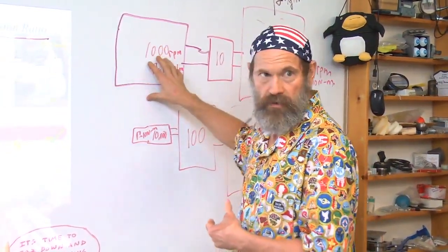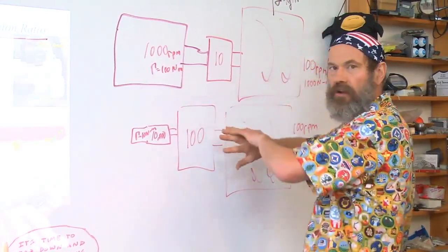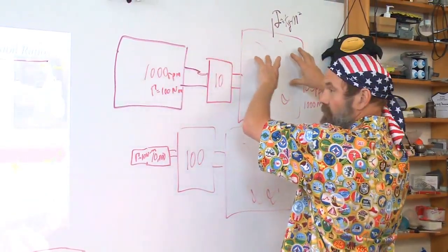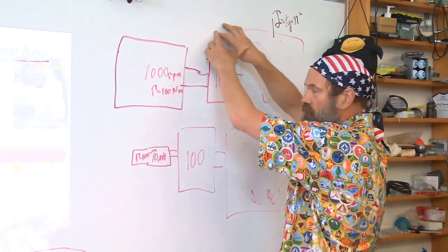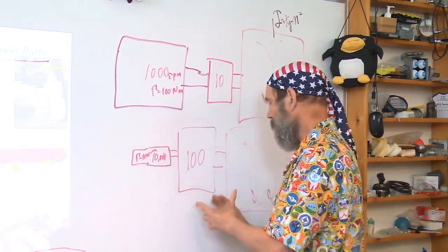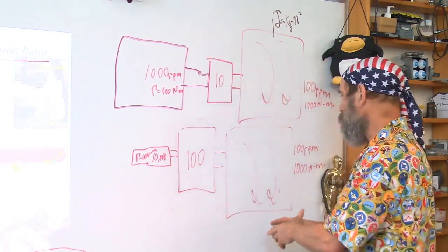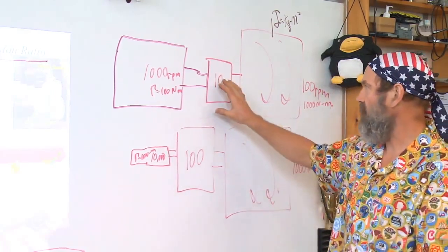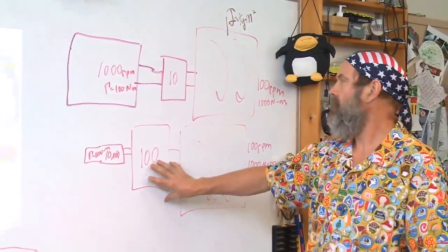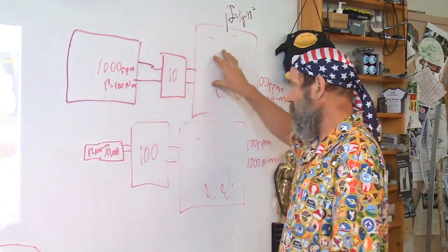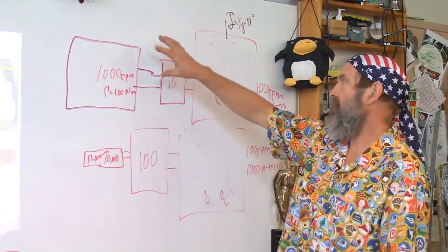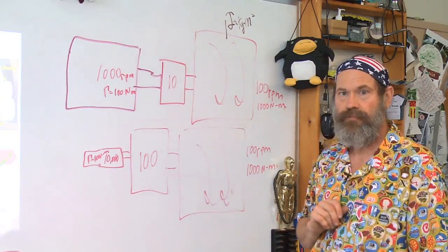So when you go to pick the motor and the load and the gearbox, they all have to work in harmony. You can start by picking a motor. Well, you have your load and see what transmission ratio that gives you. And then you can go to the other extreme, the higher speed, lower torque motor. What kind of transmission ratio is required then to drive your load? And what you'll find is that sometimes you'll get very unreasonable transmission ratios that are unobtainable, like 100 billion to 1. Very bad. So then once you get your workable scenarios, you go back and look at the physical cost of the items when you order them from the catalog, and you then minimize the cost. Okay?